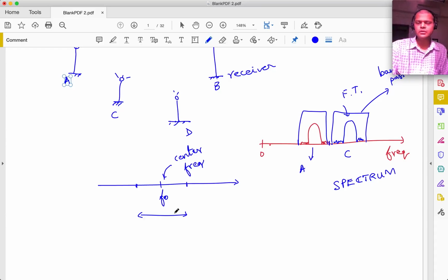So how are we going to do that? Whatever these frequencies they will tell us, and they will say you have plus or minus 10 megahertz, let's say, around this. And if you take the Fourier transform of whatever you transmit, most of it should lie within this band, and very little should go outside. Okay, so this small amount cannot be avoided.